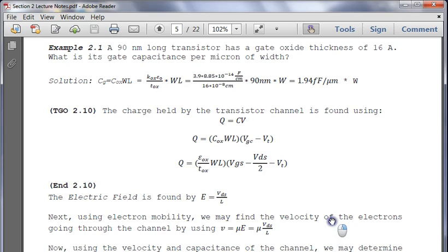But electron mobility here, the electric field is equal to VDS divided by the length. So you make that thing really, really small, and since we're trying to use 22 nanometers, 14 nanometers, there's some quantum effects that begin to take place. So electron velocity is equal to the mobility of the electron times the electric field. So then we just plug in our VDS over L there.